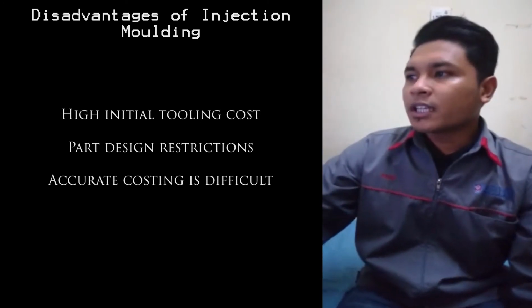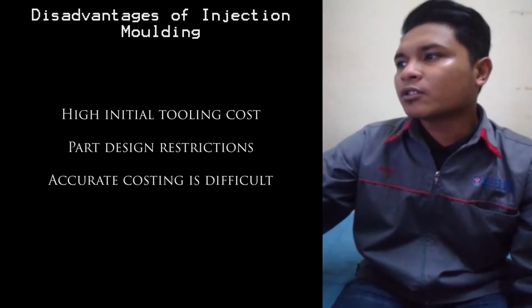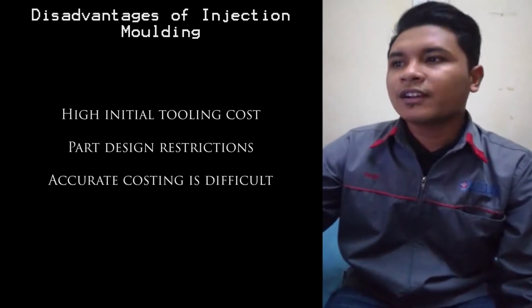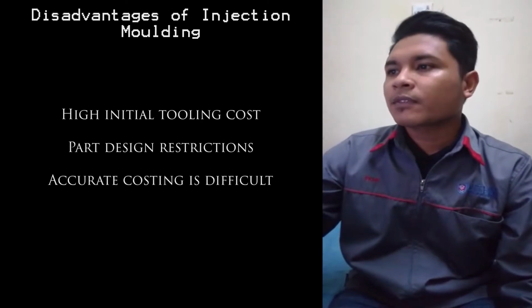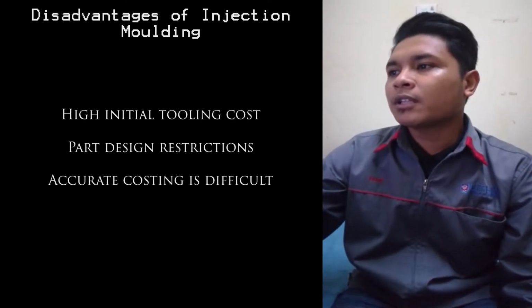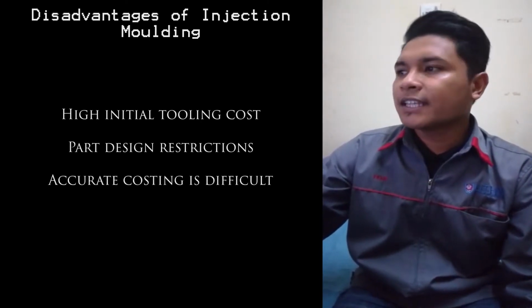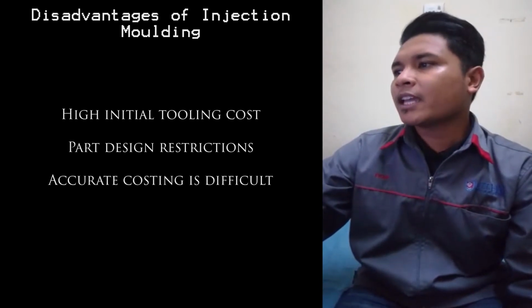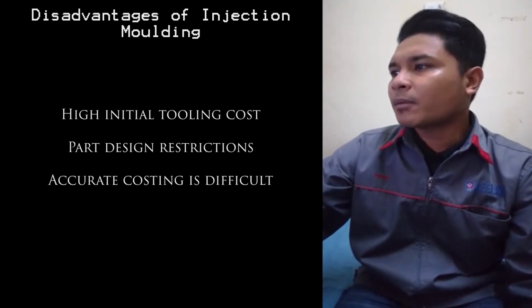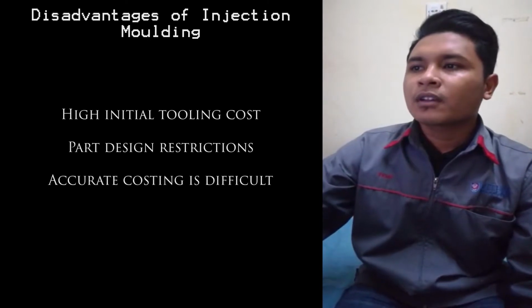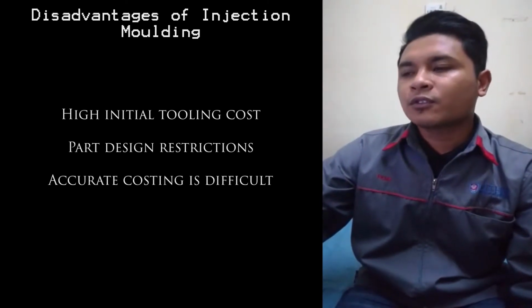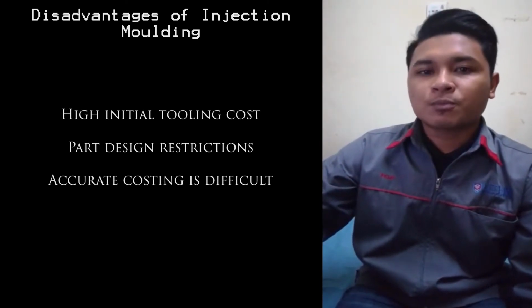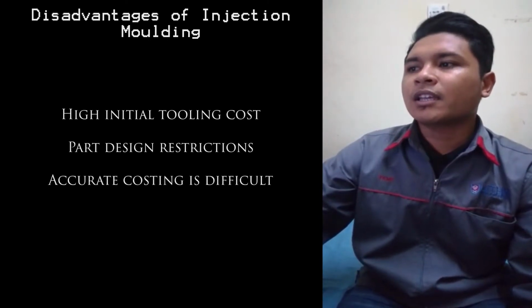The most important thing to realize is that a mold tool is made from two halves that need to pull apart, and the part needs to be able to be released from the tool. This is simple but massive. It has all sorts of ramifications down the line in terms of tool design, like each part must be made separately and be solid.